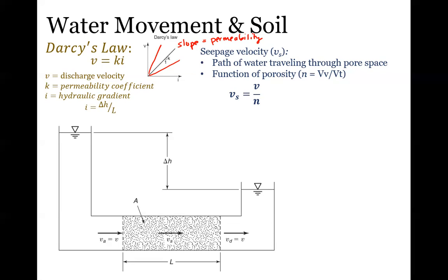If you remember from hydraulics class or whatever, Q is equal to AV. So if we're assuming Q, the flow rate, is staying the same because it's continuous, and we decrease the cross-sectional area, what should happen to the velocity? It should increase, right? You can probably picture that if you've ever been kayaking on a river: when the river is super wide, it's usually really nice and slow, but as soon as the river starts getting skinnier, the velocity of the water increases and you're going really fast on your little kayak.